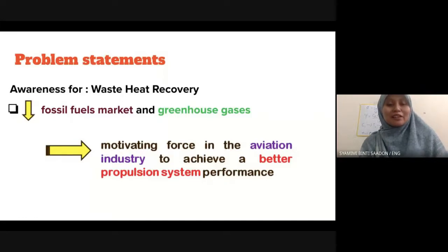And then the most important part is the thrust force produced, the thrust power, the power produced, rather than the efficiency. Depends. We still need a moderate efficiency, or moderate propulsive efficiency. But for aviation, the performance parameter which is more important is how much thrust force we can create.